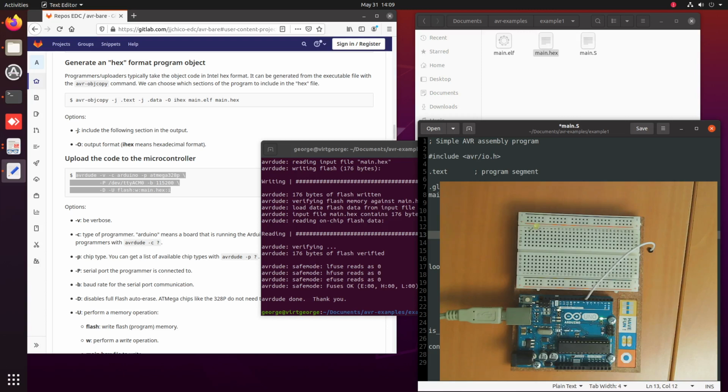So I'm going to load a value in R16, with LDI R16, and we are going to load it with a 1 here. This is the value we want to program in PORTD, 1 at the 7th bit. Once it's loaded there, it will activate the pull-up. So we store it with STS to PORTD, R16.